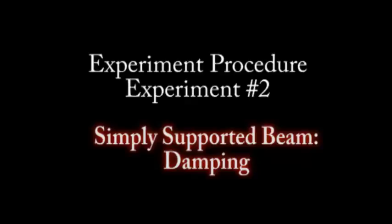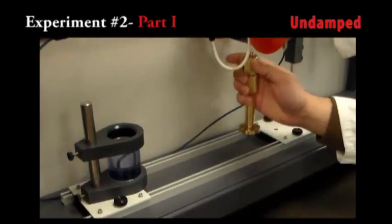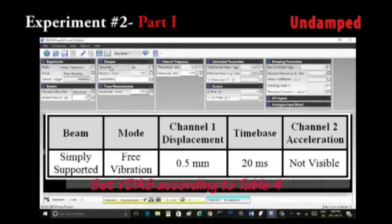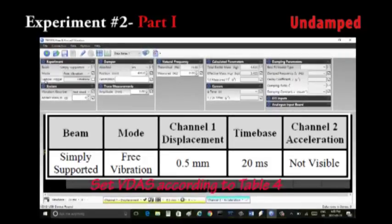Experiment 2. Simply supported beam, damping. Part 1. The first step is to set the experiment window as shown here. Fit the damper metal shaft alone under the exciter monitor. In VDAS, enter the damper shaft mass value, 400 grams, into the added mass field. Set VDAS as shown in Table 4. If necessary, readjust the set 0 control.